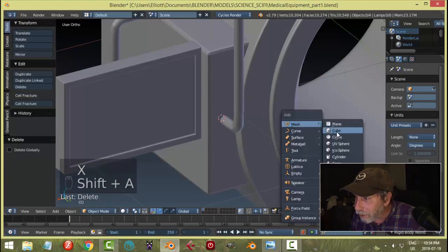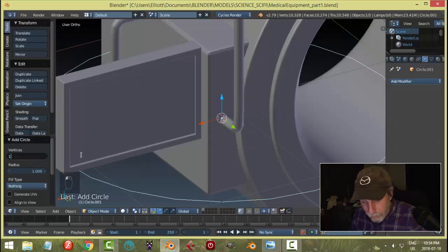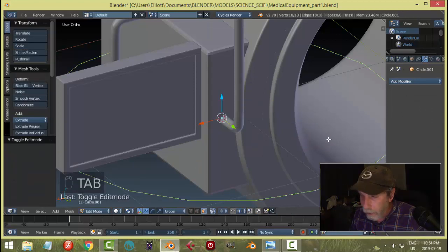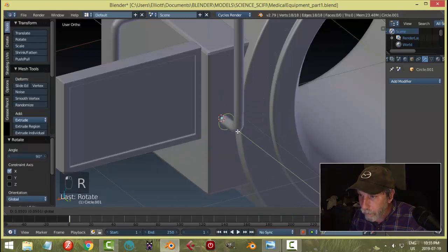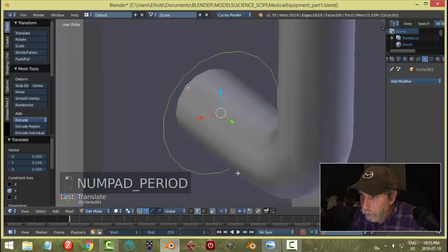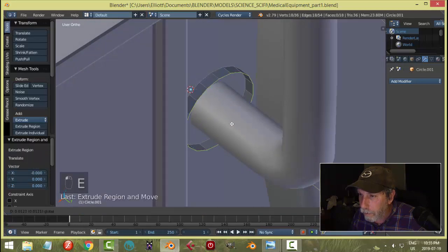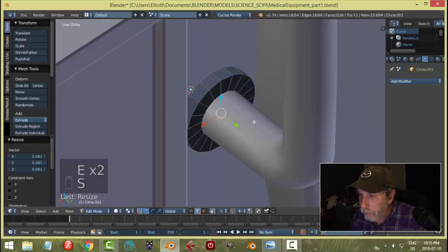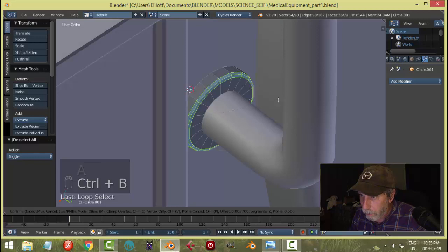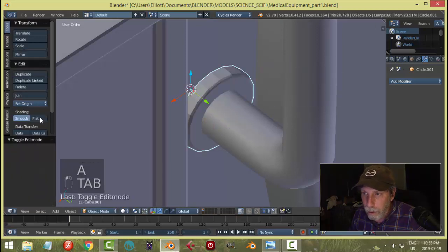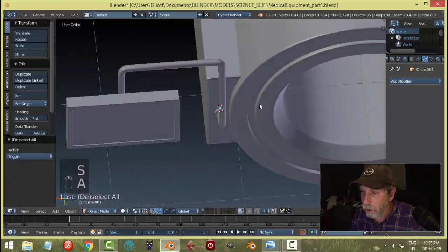So I'll bring in a circle, not a cube. Okay, slow down. That circle, I'm gonna go with 16. I'm gonna go with 18 and not use a subdivision surface. Rotate X 90. And then hit the period key to zoom in. E and S, and I'm just going to come in like that. Flip the polys. Bevel this. Maybe with 2, and now I hit smoothing, and hopefully from a distance it's going to be fine. I'll make it a bit thicker so it's a bit more pronounced.